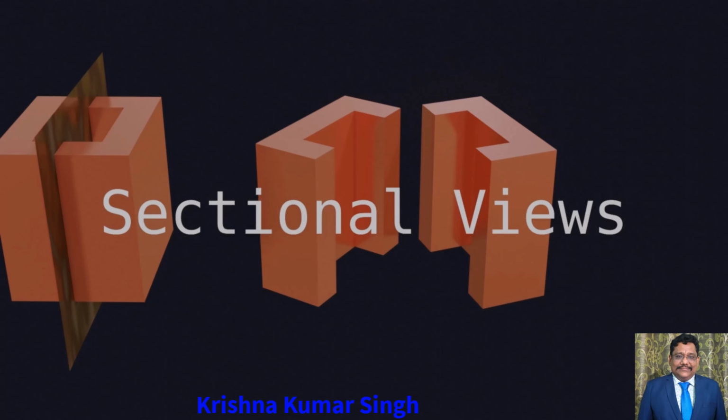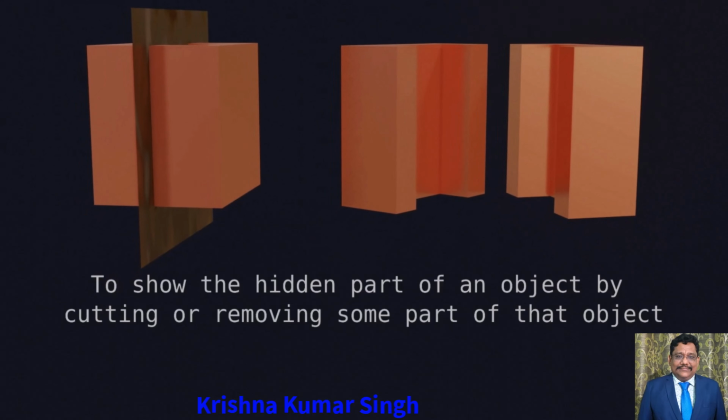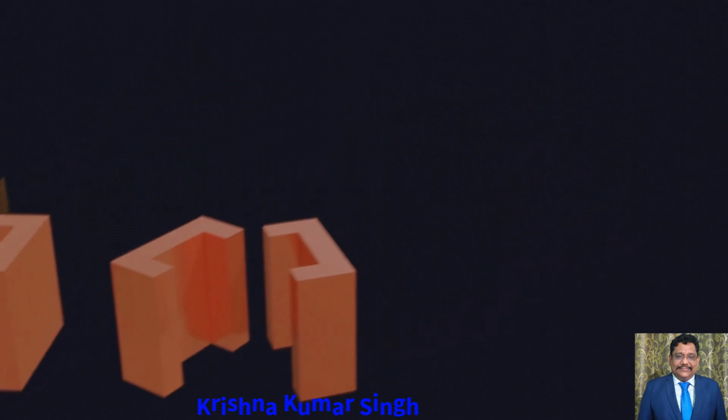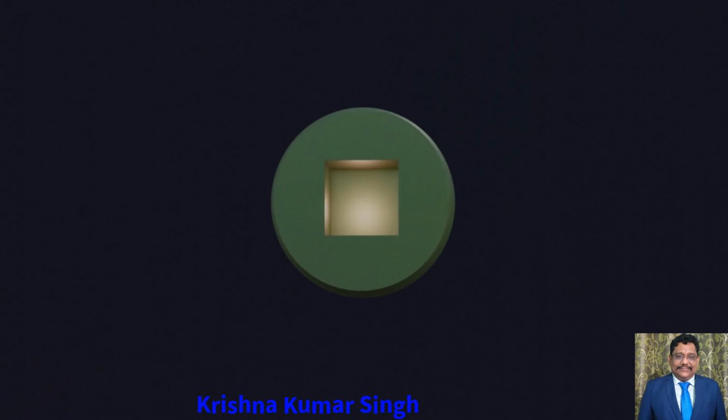So basically, a sectional view is a view on an engineering drawing to show the hidden part of an object by cutting or removing some part of that object. Now the question arises, why do we need a sectional view? Needs of sectional view in engineering drawing. A sectional view is very useful when there is geometry on the interior part of an object.